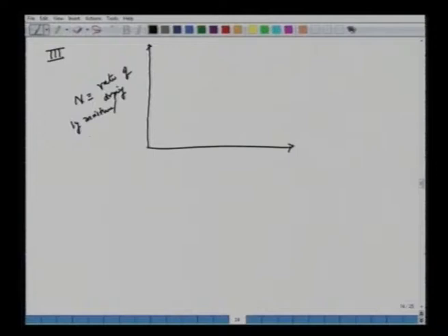We'll revisit them quite frequently. Once we have X versus time, we calculate N, the rate of drying, which tells at what rate kg of moisture is depleting from the solid surface per hour per meter square. That's the unit of this rate.